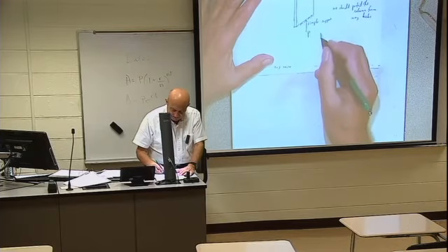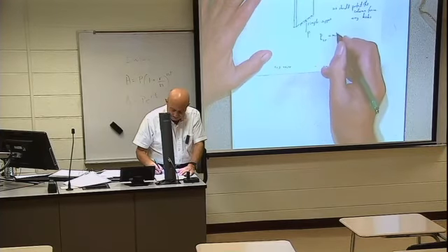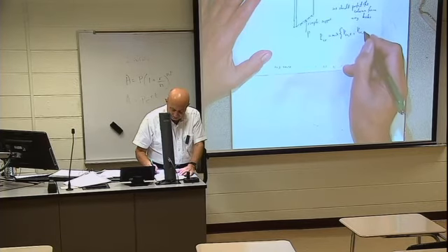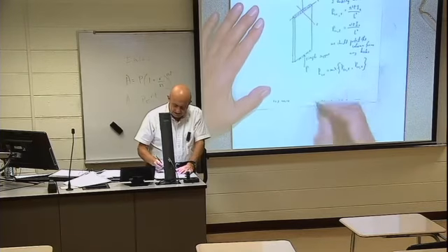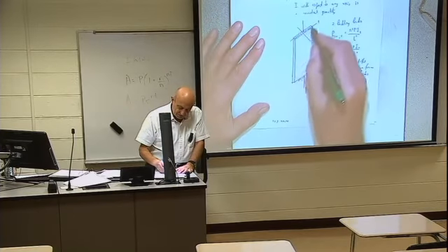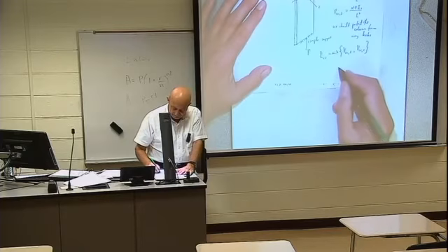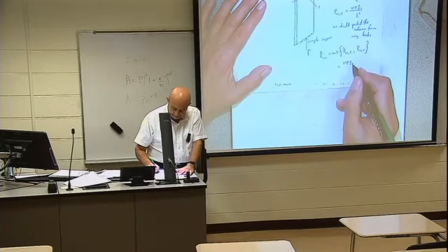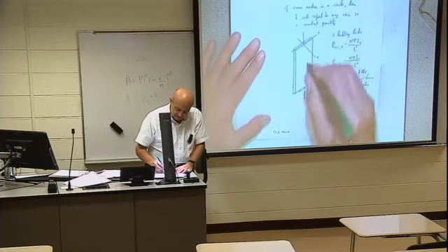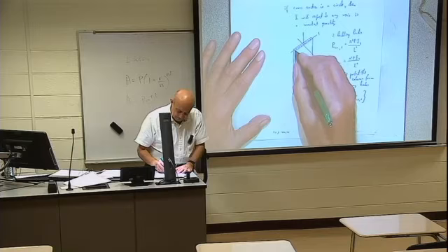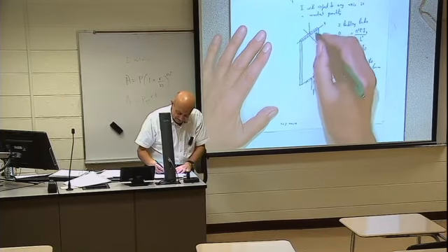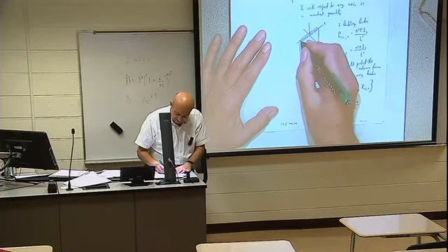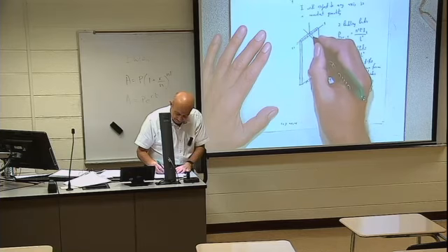So therefore, P critical, we say, is the minimum of P critical 1 and P critical 2. And naturally, the smaller moment of inertia is associated with 1. Because, look please, imagine that this is 50 and that is 100.